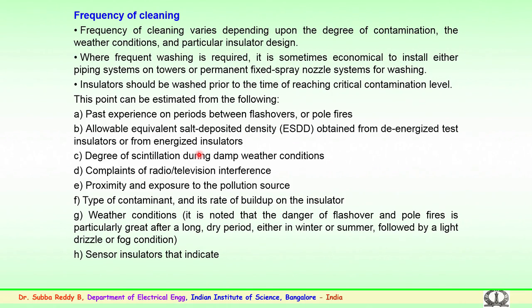Now, we look into the frequency of cleaning. What is the frequency of cleaning required? This again is an important point, where the frequency of cleaning varies depending upon the degree of contamination. So, which environment the insulators are in, or which place the insulation is in, depends upon the contamination level, the weather conditions and the insulator design. The frequency of cleaning is essential, and here frequent washing is required.